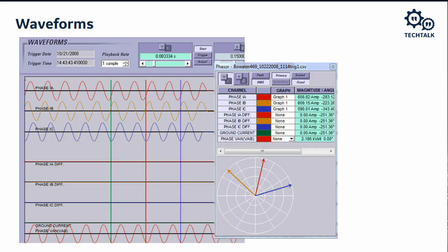But what I can tell is if I look at the phasors, immediately, right off the bat, one of these currents is not correct, right? So the phasors that you see there, the vectors that you see there, those are the vector diagrams for the currents to the motor. And looking at this, it looks like the red vector is in the wrong direction, right? So take a look at that. The red vector is in the wrong direction, so it looks like if I merely swap polarity and non-polarity on the red current, that I can take care of this problem.